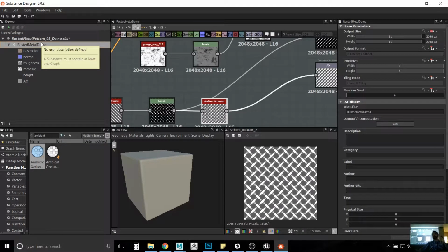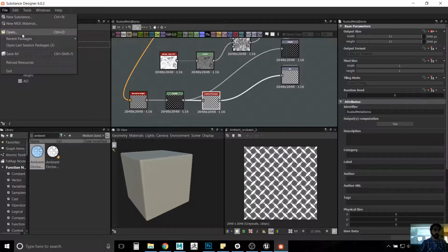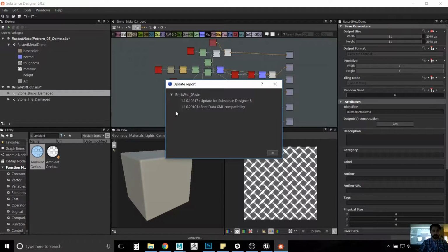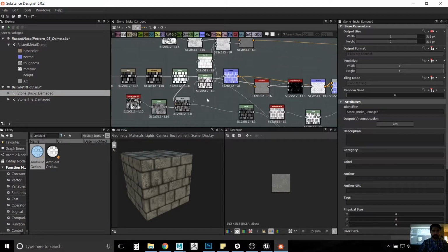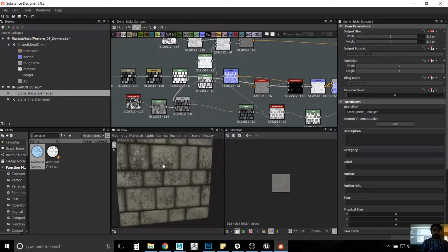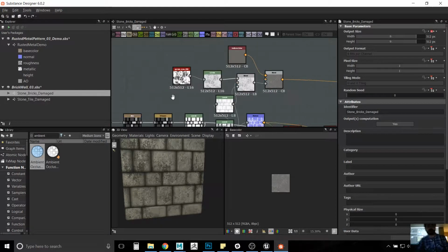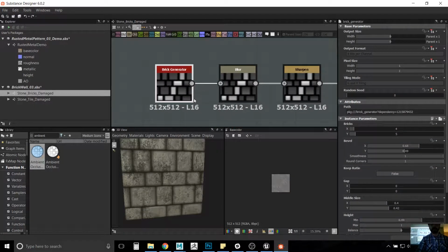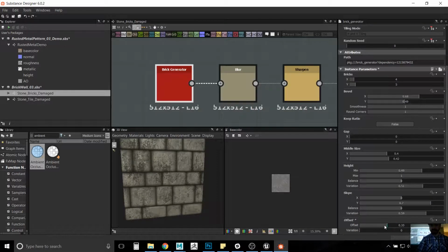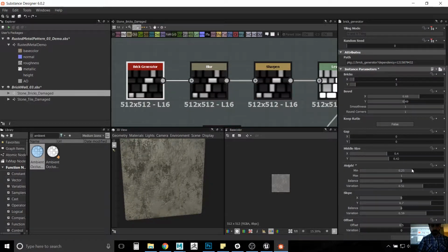Okay, so that's the Substance Designer demo. To give you an idea of what some other graphs might look like, it's overwhelming when you look at a finished one, but when you build it yourself, it's fairly simple. So something like a brick pattern here is pretty, for the most part, straightforward, just using various grunges and initial nodes for a brick generator, with varying things for the slope, offset of those bricks, blurring, sharpening them, changing the overall height difference between them.